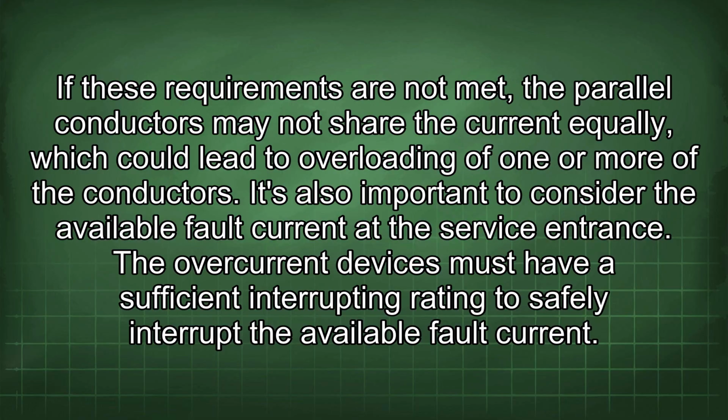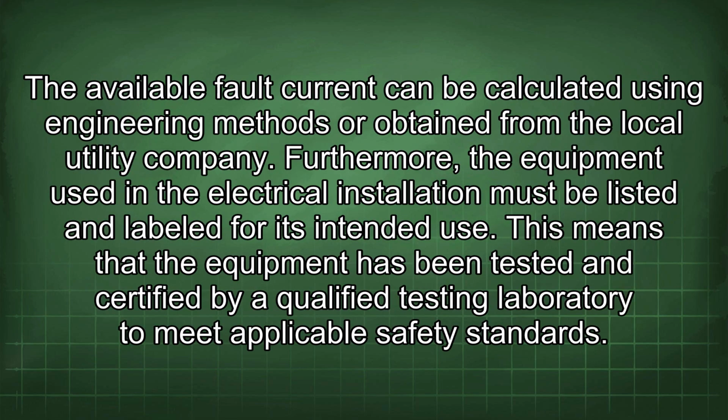It's also important to consider the available fault currents at the service entrance. The overcurrent devices must have a sufficient interrupting rating to safely interrupt the available fault current. The available fault current can be calculated using engineering methods or obtained from the local utility company.